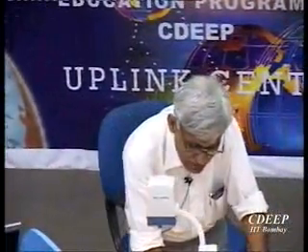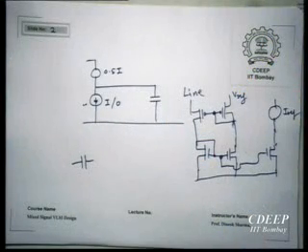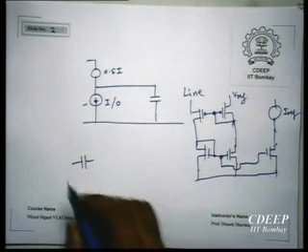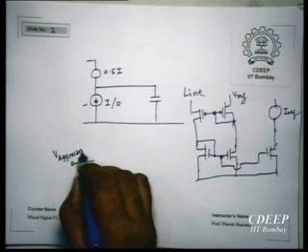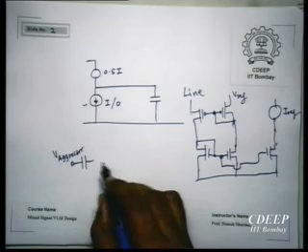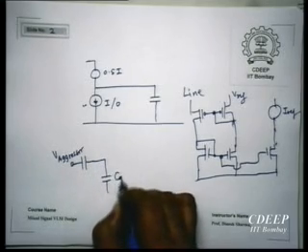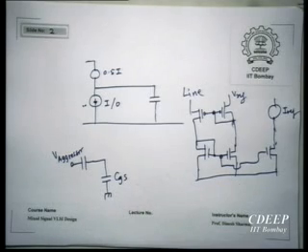This is not susceptible to noise. What happens is that if you have something connected to ground through practically 0 input impedance, the noise sources are like high impedance sources, stray capacitance and so on. So essentially, suppose this is your stray capacitance. What happens in the voltage mode? This is your aggressor voltage. In voltage mode this goes to a transistor. This is your CGS. Correct? So the voltage division takes place here and you get relatively large voltages.